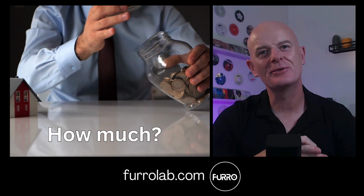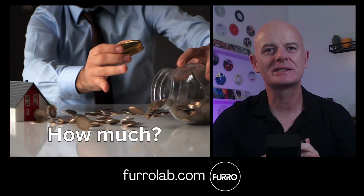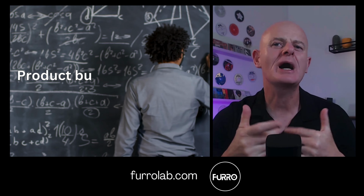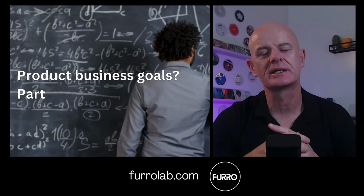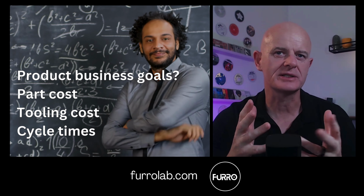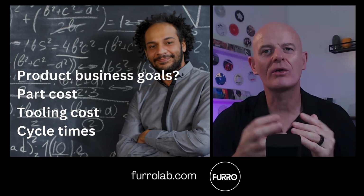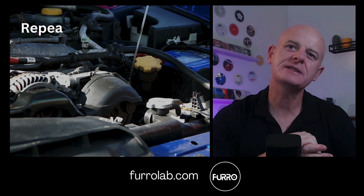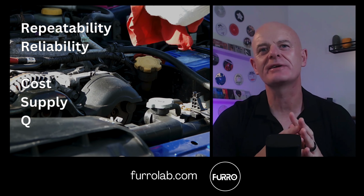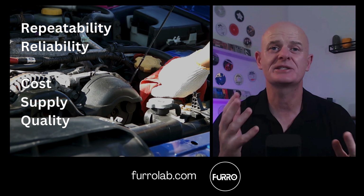Cost is usually one of the first questions you will get. Yeah, it looks great, but how much will this thing cost us? So how do we hit the business goals of the product? We need to focus on things like part cost, tooling cost, cycle times. These all contribute to the bottom line. Process repeatability and reliability is a key consideration that affects almost everything. It affects cost, supply, and quality.